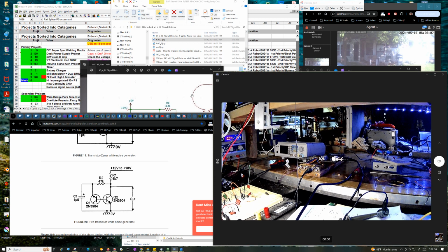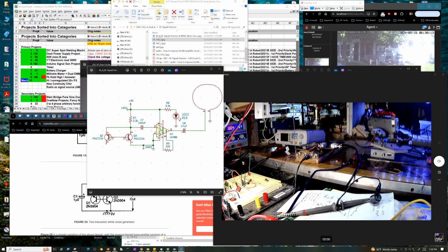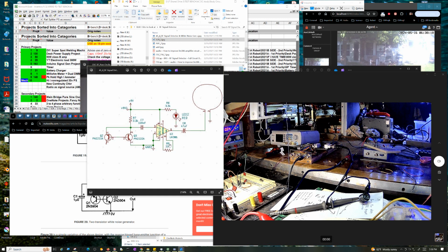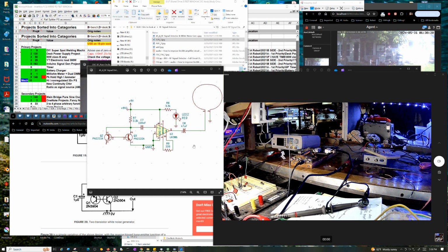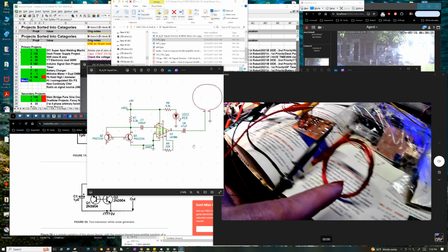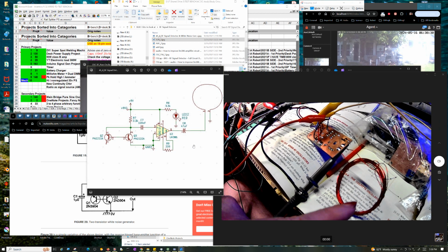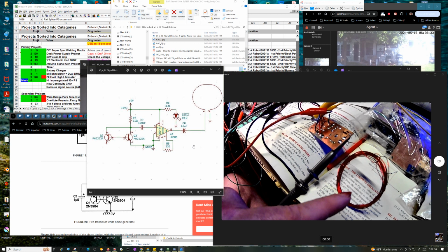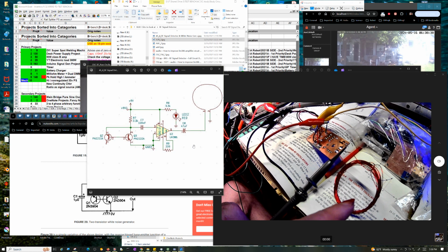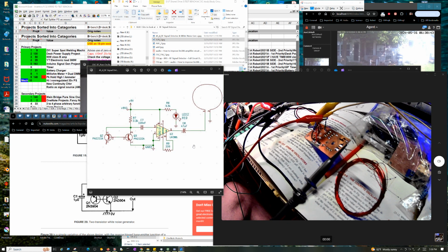And the idea was to take this noise and stick it through a 386 audio amplifier, right? He's got it set to like a gain of 200, but then to stick it through a coil and make a signal injector. You can see the coil there, but it's supposed to be a noise signal injector, and he specified I think 1 loop of wire or something, but I think that's just going to stress out your amplifier if you do that, and you can get the same benefit with multiple turns. I got like a 10 turn coil here.